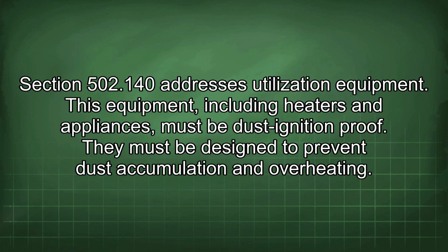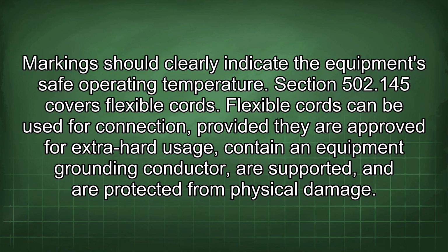Section 502.140 addresses utilization equipment. This equipment, including heaters and appliances, must be dust ignition proof. They must be designed to prevent dust accumulation and overheating. Marking should clearly indicate the equipment's safe operating temperature.